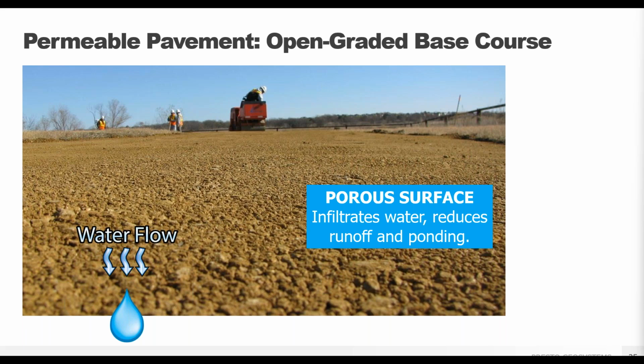As a rule of thumb, a 3/4 inch or 19 millimeter open graded crushed aggregate has a void space of approximately 35%. So you can calculate how much water you can store to potentially reduce stormwater runoff and ultimately have the ability to reduce stormwater pond volume and land requirements. See any of our in-house engineering team members for help with calculating stormwater requirements for your project.